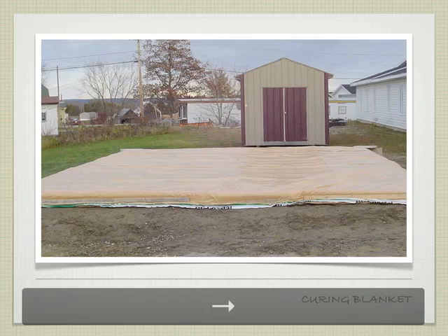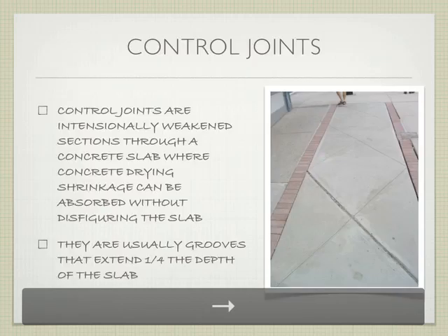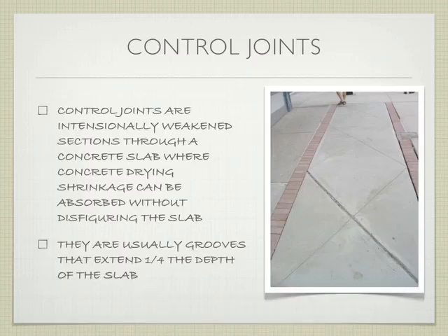So you saw this slide last week, but this is a curing blanket. It's a plastic sheet that you put over the slab to make sure that moisture stays in and doesn't dry it out. So, different methods. Obviously, if you cover it with sawdust, it's a bit cheaper because you're just using a byproduct, especially if you're somewhere close to where there's a bunch of sawdust shavings.